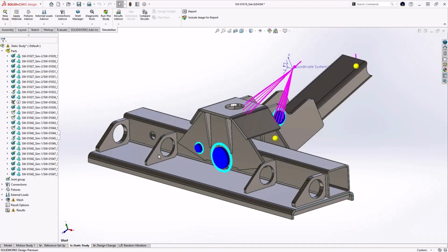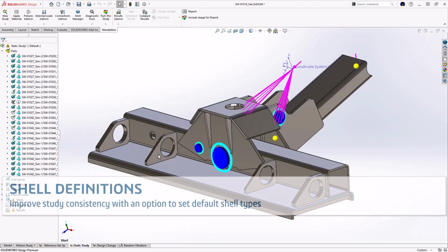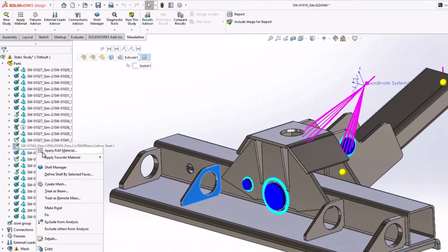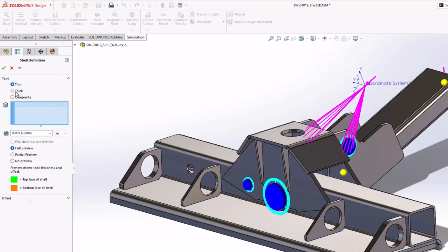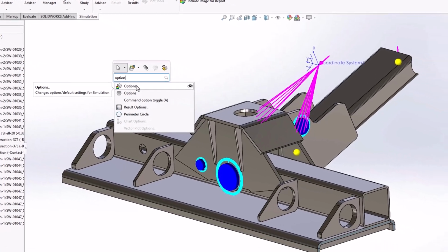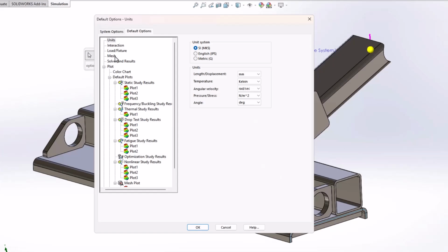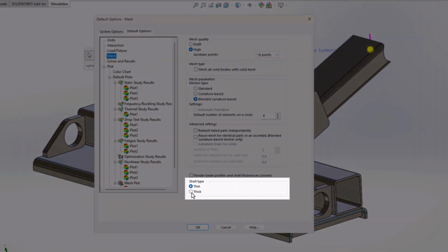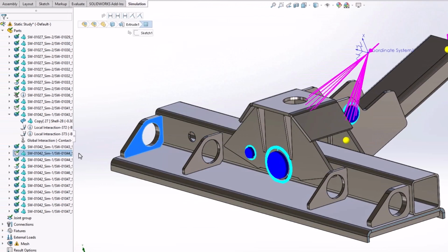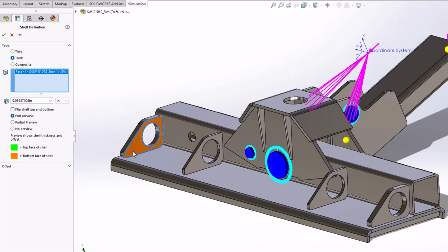This model is set up primarily using shell elements, ideal for analysing thin plates while ensuring fast solve times and retaining accuracy. Typically, a thickness to span ratio is used to decide between thin and thick shells, where thick shells will account for shear stresses through the plate's midplane. New in Simulation 2026, you can now set the default shell type directly in your simulation options, with thick shells as the new default. To reduce rotation, we can adjust the plate thickness through the shell manager.